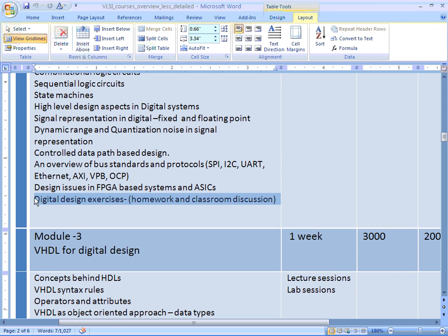For example, I have explained Spartan 6 FPGA IO standards as a part of our interface standard session. Then, when I give you a question paper that says, in Spartan 6, is LVDS supported? If so, what is the common mode voltage and what is the differential swing required? Got it? We are not expecting you to memorize and answer, because nobody needs that in the industry either. You should know how to browse the data sheet, which table to refer to, and how to get the answer.